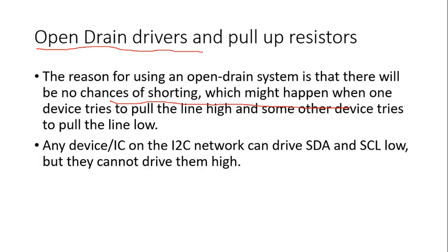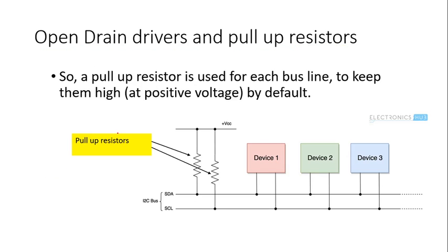Then to connect these open drain drivers, it is using pull-up resistors. Okay, any device on the I2C network can drive SDA and SCL low. Means these two lines, they can pull them to the low, but they cannot drive them high. Okay, means here a pull-up resistor is required for each bus line.